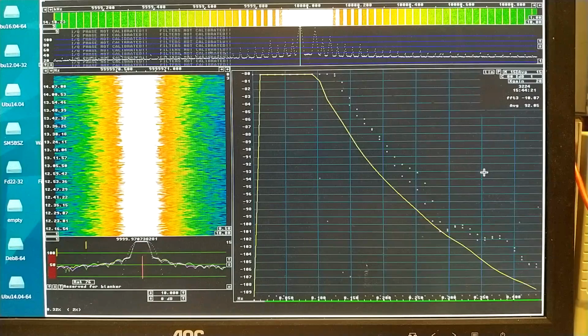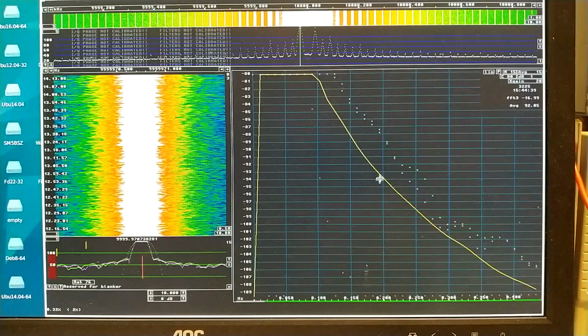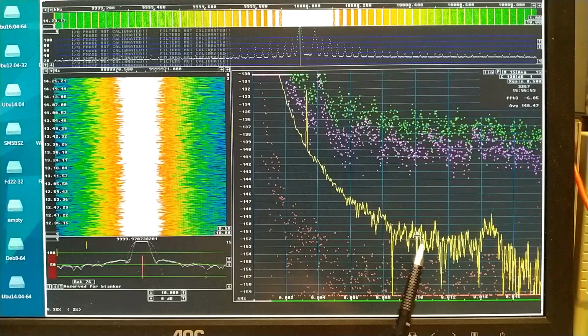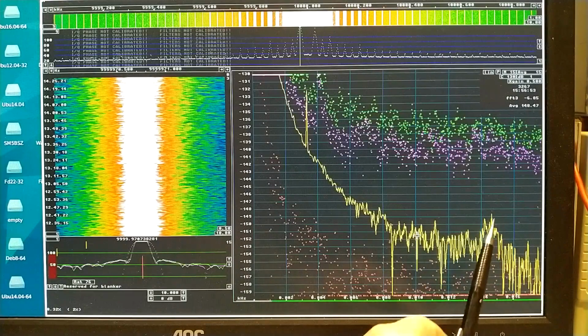It's easiest to read the values in the linear frequency scale. So I can see at 0.2 Hertz it is minus 94.0 dBc per Hertz. I can read frequencies up to almost 10 Hertz. That's here. This starts to be perhaps a little uncertain because I have a phenomenon here.